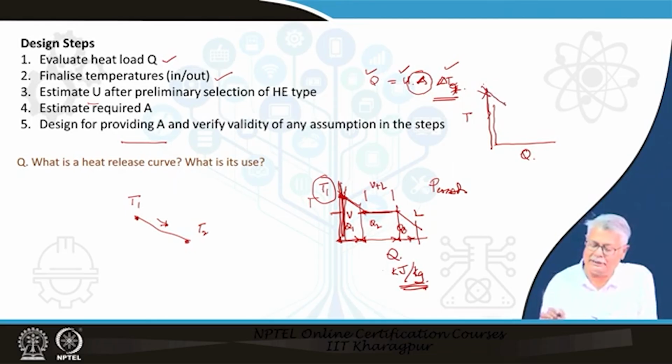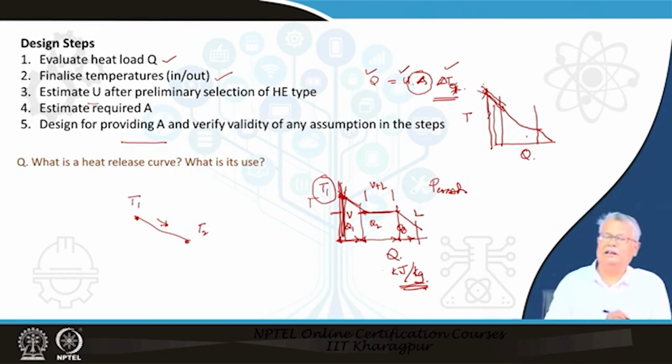You have a line like this, then you have a bend, and the removal of the vapor and the liquid is not over a constant temperature when you have more than one component in your mixture. And this basically is the point of condensation, which is the dew point, and this temperature is the bubble point of your component at constant pressure.